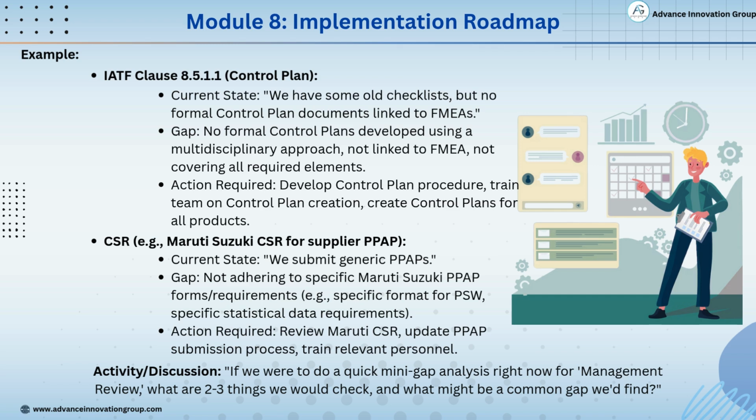CSR, like Maruti Suzuki's CSR for supplier PPAPs. Current state, we submit generic PPAPs. Gap, the PPAPs don't adhere to Maruti's specific requirements, like the correct format for PSW or statistical data requirements. Action required. Review Maruti's CSR carefully, update the PPAP submission process, and train relevant team members accordingly.